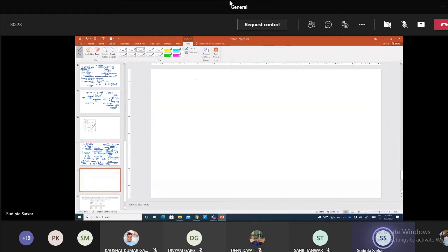So let me write this equation again. Head loss per unit length of the filter is f into 1 minus e divided by e cube, into 3 by 4g, into Vs square divided by psi d, or you can write dp, whatever the diameter of the particle. Here Vs equals Q by A, where Q is the flow rate through the filter and A is the cross sectional area. You can recall that this is the same classical formula that we know as the Carman-Kozeny formula that we have always been using for our purposes.